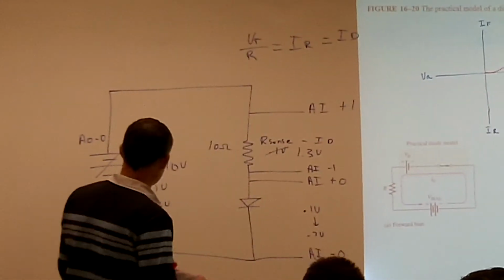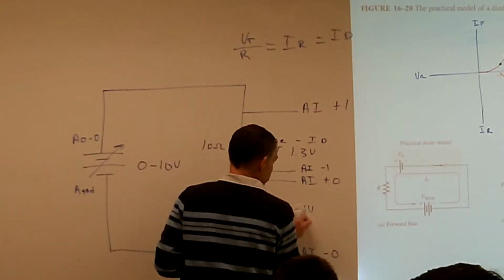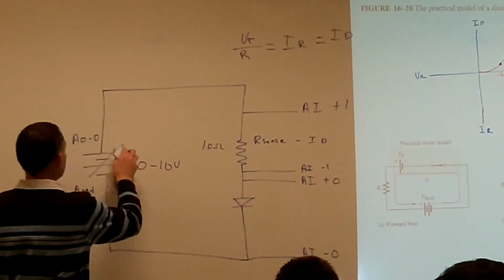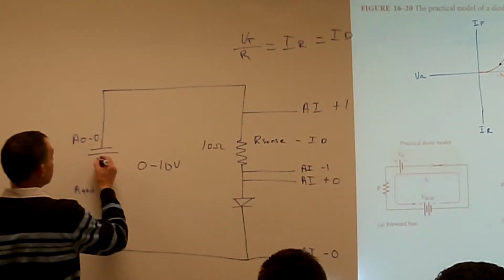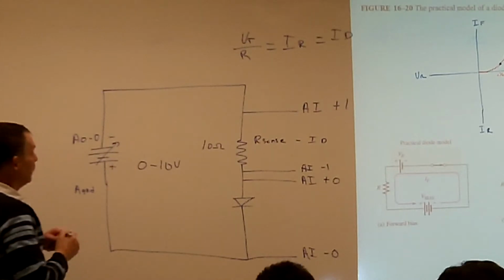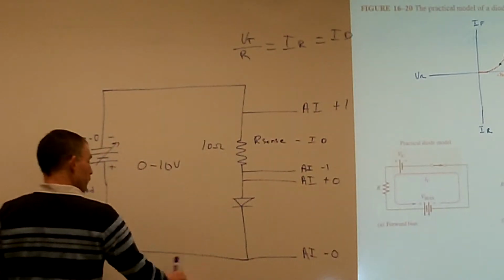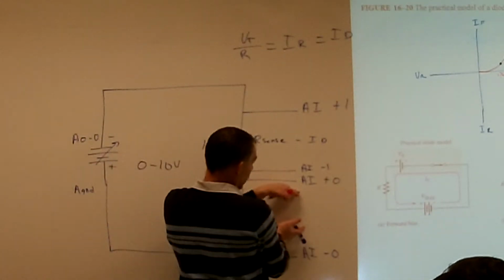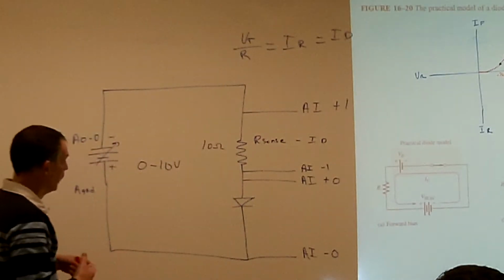Okay, then what we're also going to do is reset it up, or we don't have to reset it up, but the MyDAC will set it up. And what it's going to do is flip the power supply around. Now I'm going to be more negative on this side. This is going to give me my reverse biasing situation. And it's going to do the same thing. It's going to sense the voltage going across the diode, look at the sense resistor, and calculate out the current.